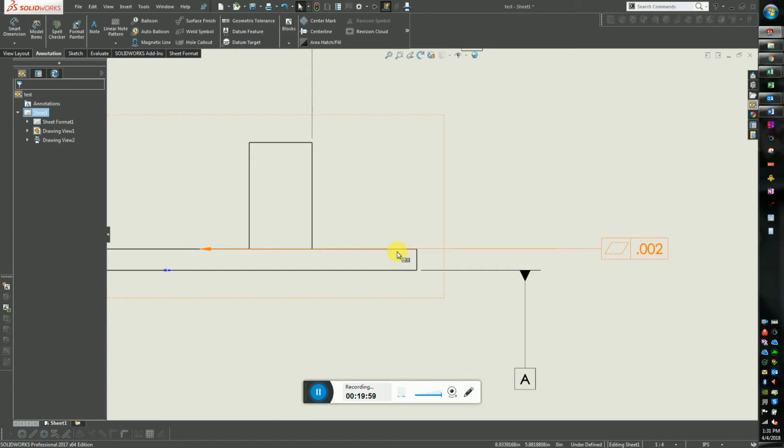Anybody know how they would measure that? With a dial indicator, or some sort of probe, when they move it across. A dial indicator would probably be the easiest way to do it. They could put the dial indicator right on the machine head, and then just run the table back and forth, and they could watch the dial and see how much it deviates.